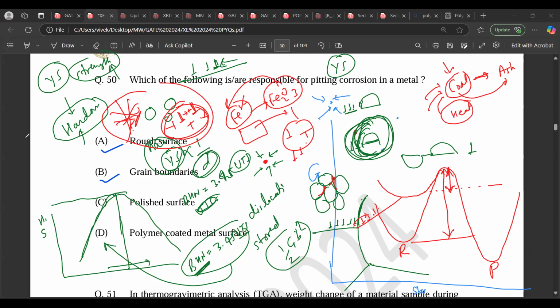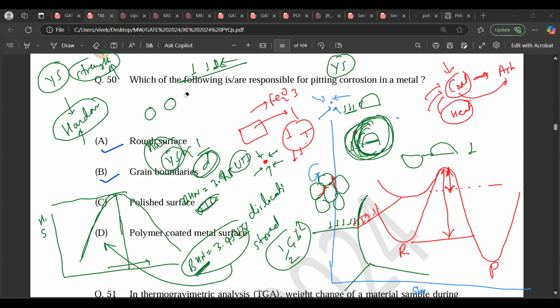In the same sense, how do you measure hardness? Hardness is nothing but the resistance to localized deformation, or resistance to indentation. When you indent your material with a diamond tip or steel ball tip, the size of the indent, the diagonal, defines the hardness number.